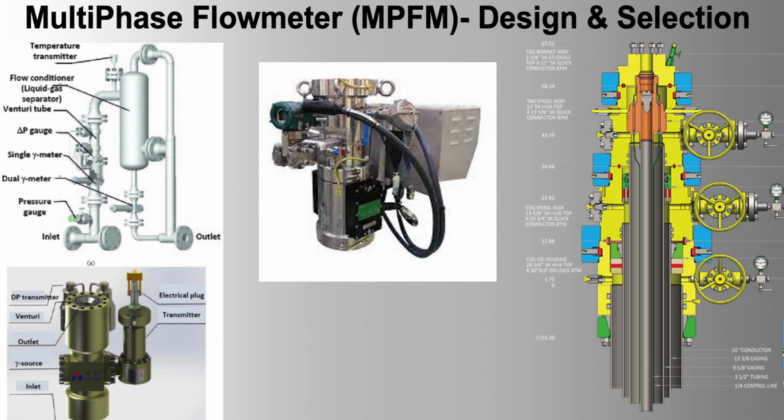2. Orientation. Vertical or horizontal. Select appropriate orientation based on the flow meter design and installation guidelines. Ensure the flow meter is installed in the correct flow direction as specified by the manufacturer. 3. Accessibility. Maintenance access. Install in locations that are easily accessible for maintenance and calibration. Space requirements. Ensure adequate space for installation and removal of the flow meter and associated equipment.